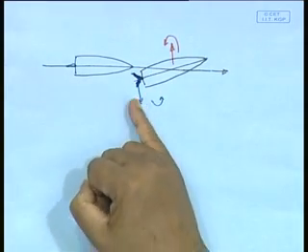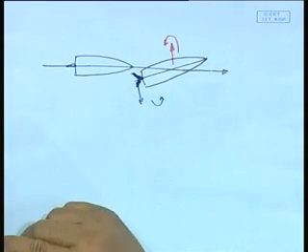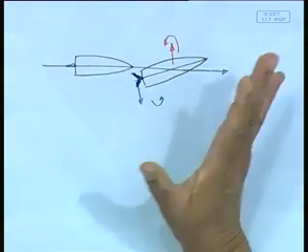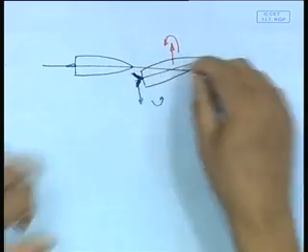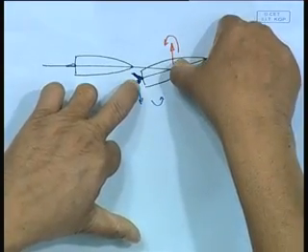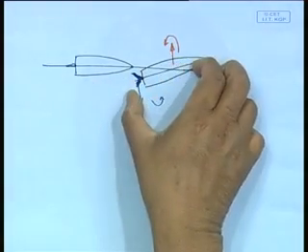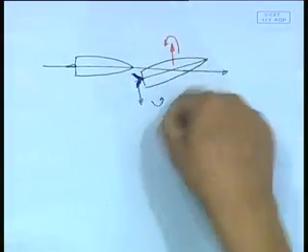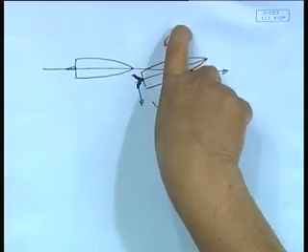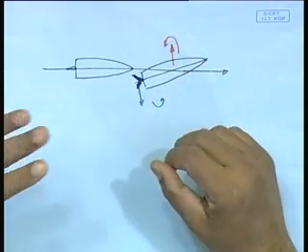See, the rudder of course is giving the force because of the flow past it, it is a control surface. But I am somehow causing a y direction force, a transverse force on the rudder. And that transverse force is going to give me a moment of the hull about the CG. So I am introducing a force in this direction and a moment in this direction to try to turn. Now my ship is turning.